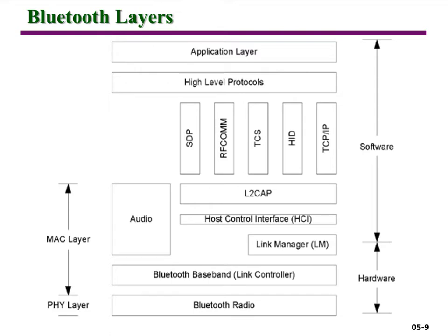Okay, so it's TDD for bidirectional communication, and TDMA, which means that each slave or each node sends in the uplink in the time slots that's assigned to it, so there's no collision.